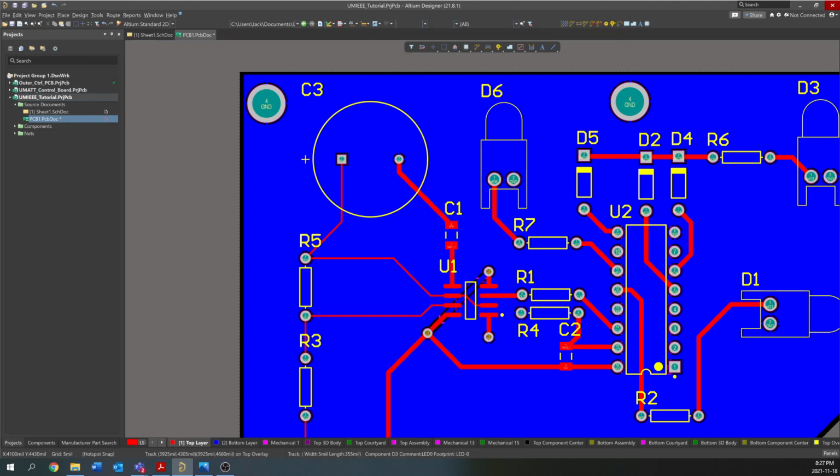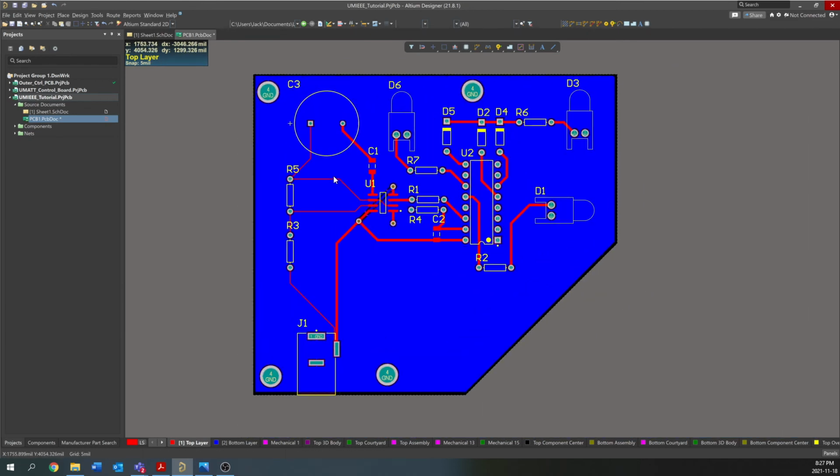So Lucas is asking, is there any reason why you wouldn't put a copper pour on both layers? And that's a great question. We could do just that. Generally, yes, you would put a pour on both layers. You can think of a more complex board with more signals. Maybe you have to route even more signals on the bottom side, and it may work out that one half of the pour gets split from the other half.